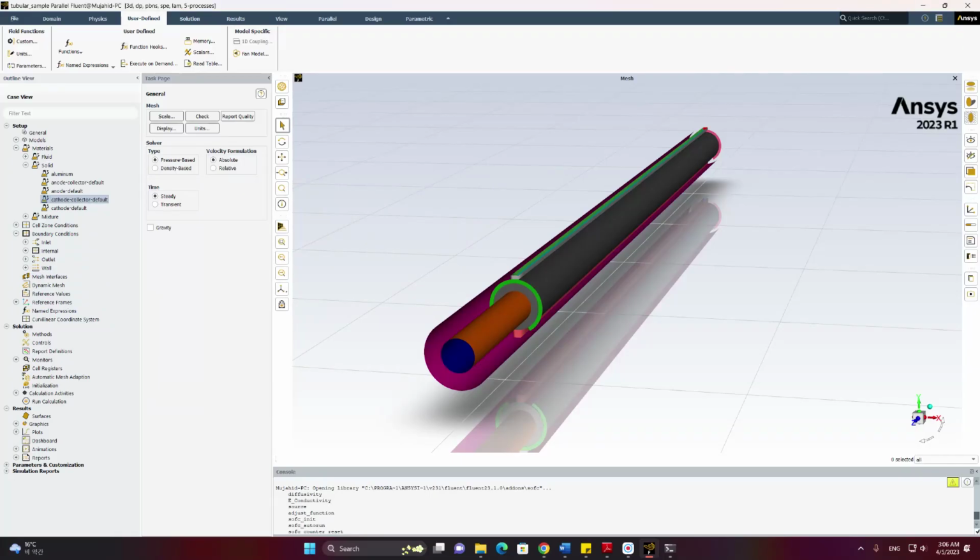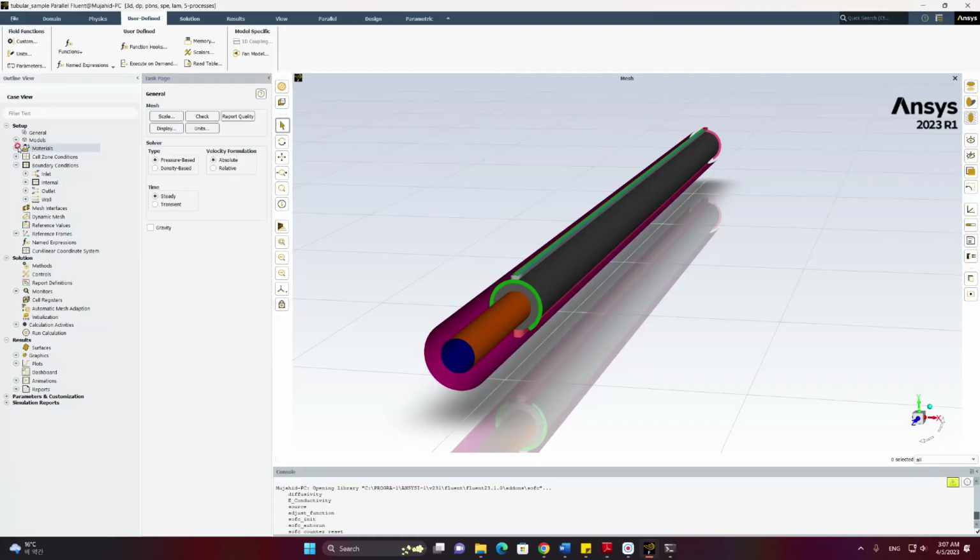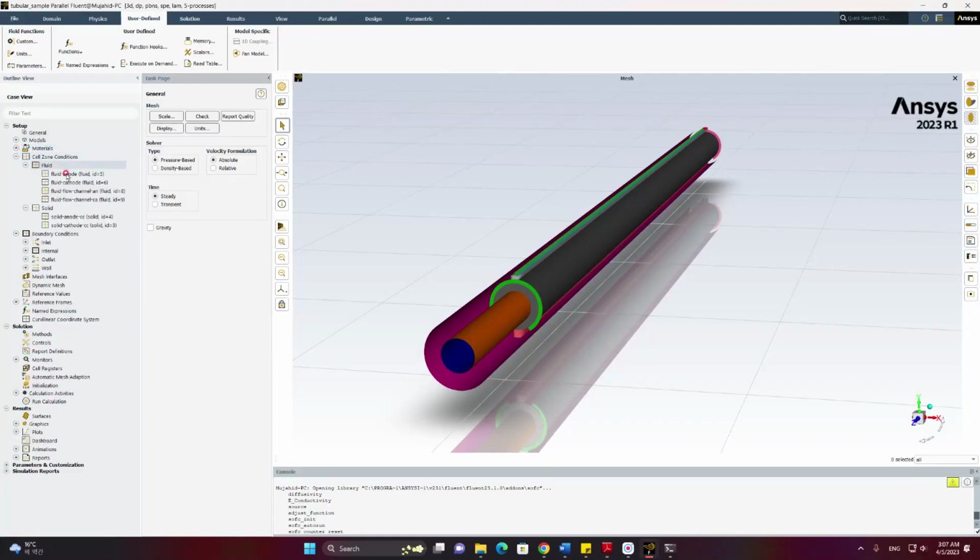Now we have defined the material, and it mentions that the SOFC mixture only accounts for H2, O2, water and nitrogen. In case CO electrochemistry is disabled, then the relevant species CO and CO2 need to be added into the mixture by the user. Right now we have defined the materials, and now we need to apply them to the zones.